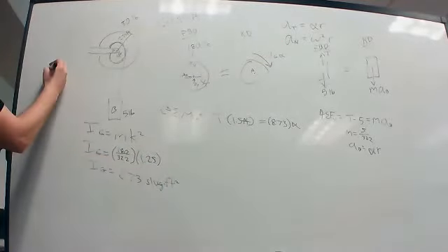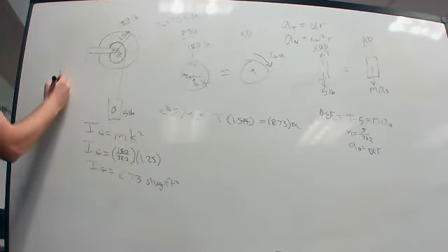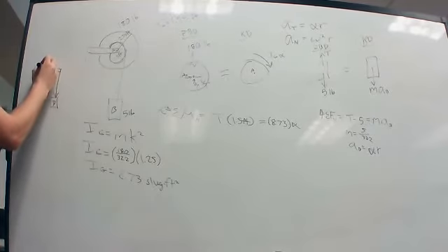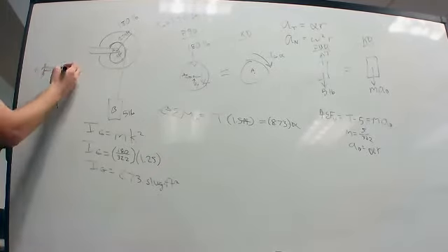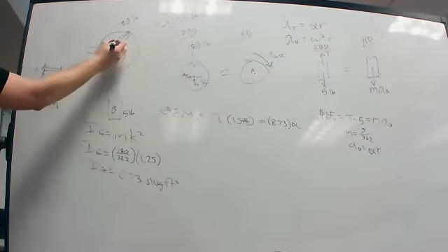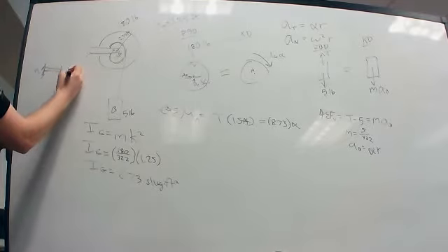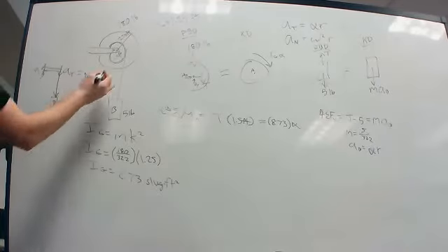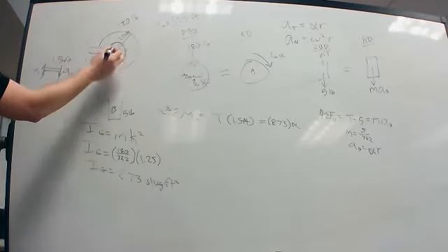What we're saying is that B is the same as the rigid stick here, with this being A and this being the point where the cable meets the wheel. And so this acceleration would be AT, and AT is alpha R. R is, in this case, 1.5 feet, known from here.